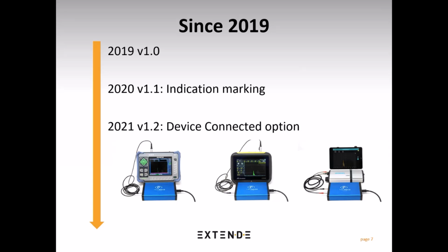This is an electronic device plugged into the laptop with a USB cable that allows you to practice with actual flaw detectors. It works with all the flaw detectors of the market. For instance, the Sonatest Wave, Olympus Epoch, GE USM-GO. The signal from TraiNDE UT is then directly displayed on the flaw detector. And you can use all its features, like the filters, the calibration, the DAC, the gates, etc.